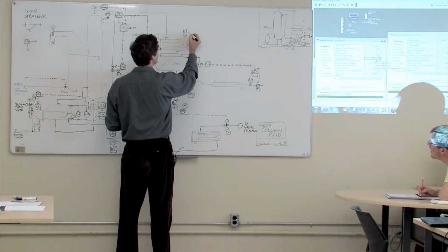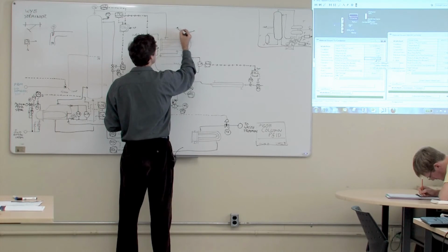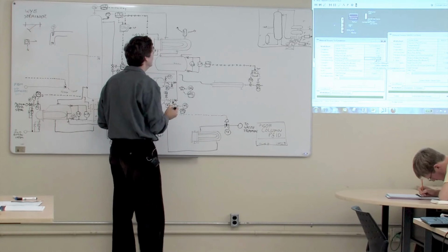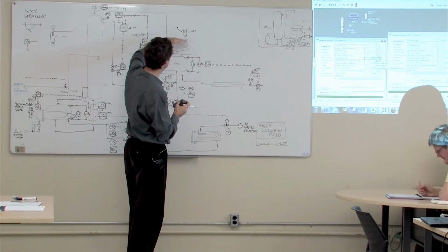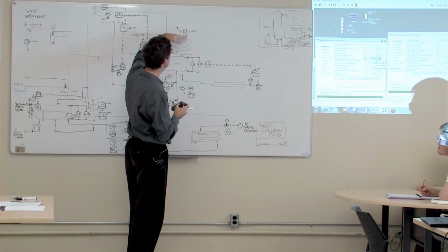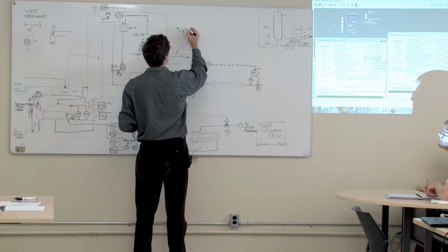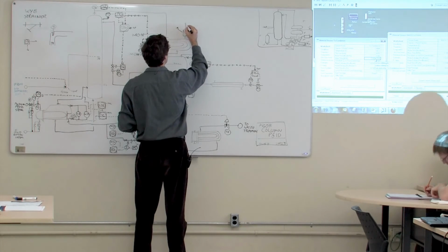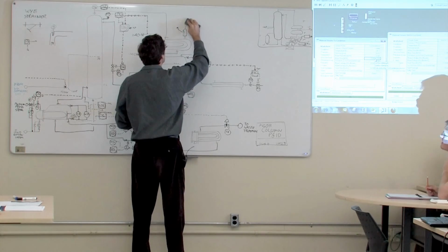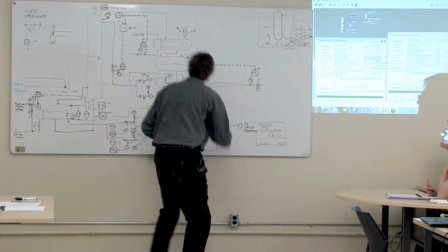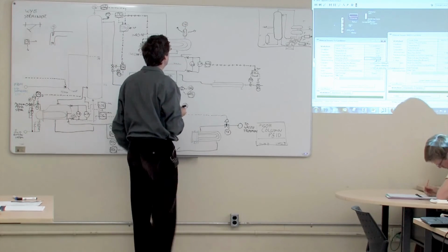So what'll happen is the radiant and convective heat losses from this will allow the gases to cool, and there's no condensing methanol in there, so it just keeps on cooling basically down to ambient temperature. And so we can detect whether we have non-condensables in there simply by putting a TE in there.